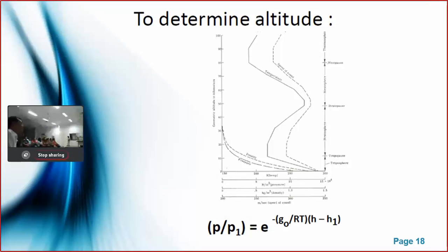So we can use the pressure and temperature sensor BMP180 or BMP085, or we can use the GPS, as one of the data that the GPS module receives is the altitude of the module, which is already integrated in our CANSAT.